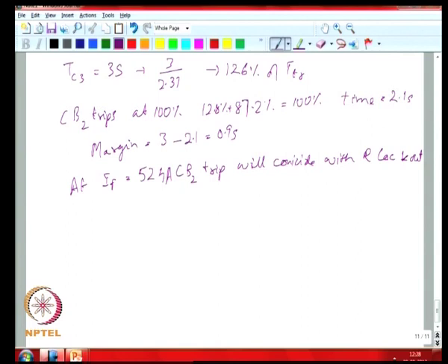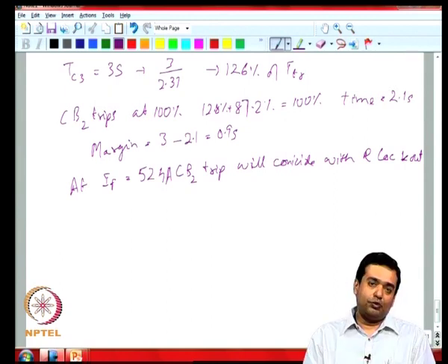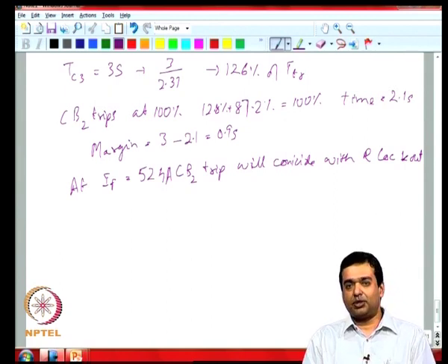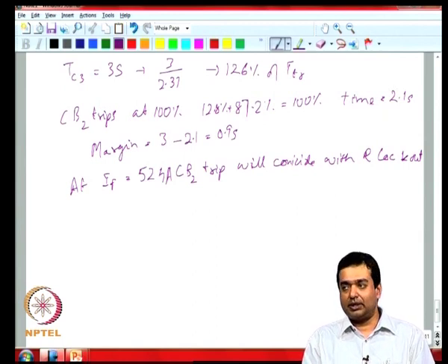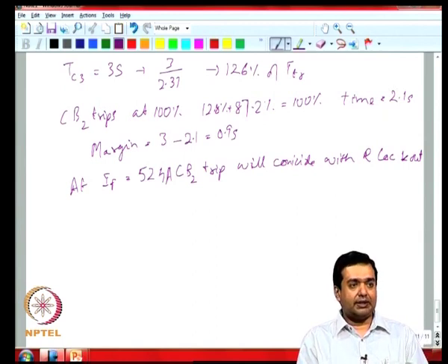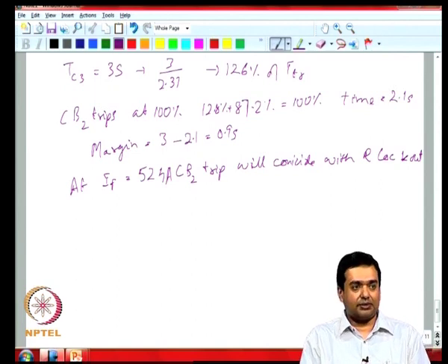Though in typical protection coordination practice, you typically design the upstream protection before you decide on what you do for the downstream, in some of these situations, you will have to look at the entire situation to decide on what should be the settings, so that you do not have nuisance trips. Okay.